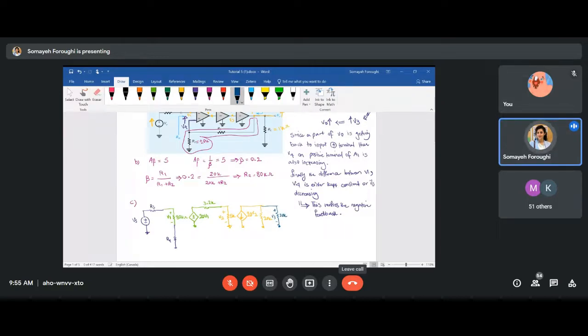It is connected to, let me clean this part, I'm going to write it down later. It is connected to the other end for the gain, and the gain is a unity gain. So it means we have V3 over here, and now you have your output resistance, which is 1 kilo ohm. And then you have your load, and that's it. On the other end, you will have the V output, and you will have the load here, RL.